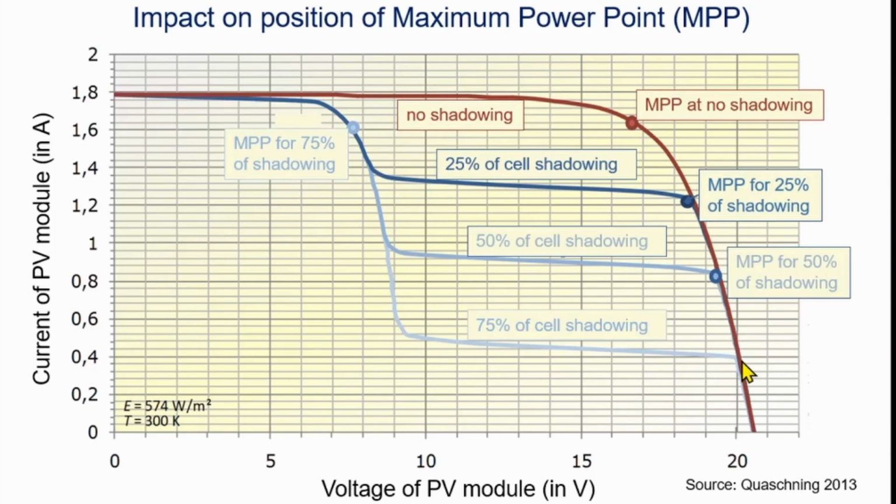Only if you do a full swing along the full range of voltages will you find that maximum power point. So this depends on the algorithm, the strategy of the maximum power point tracker, whether you just do a differential tracking here or whether it does a full tracking over the full voltage. Sure, it takes longer to do that, because you have to carry out all the multiplication to find whether the power is increasing or decreasing. But in the end, you have the best results.